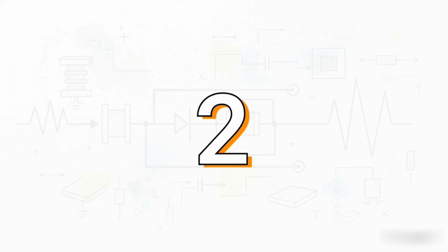And get this, for this exact waveform shape, the biggest troublemaker, the loudest piece of noise, is always at double the input frequency. So if your input is 60 Hz, your biggest problem is at 120 Hz. And knowing that is huge because it means we can design filters to specifically target and eliminate that one frequency.